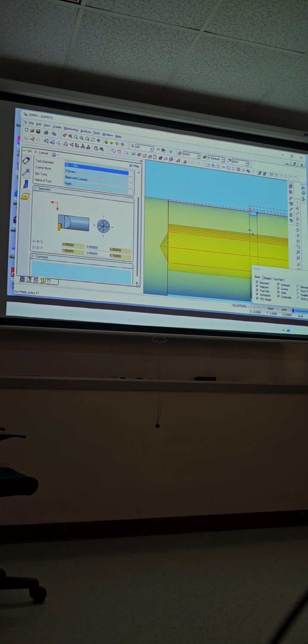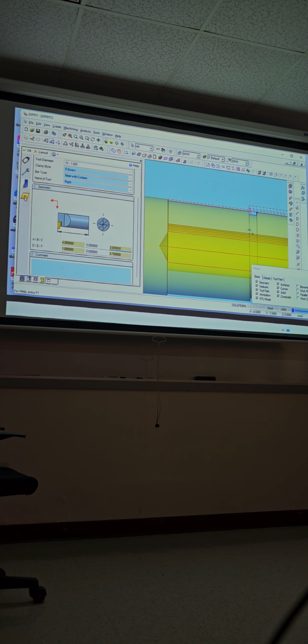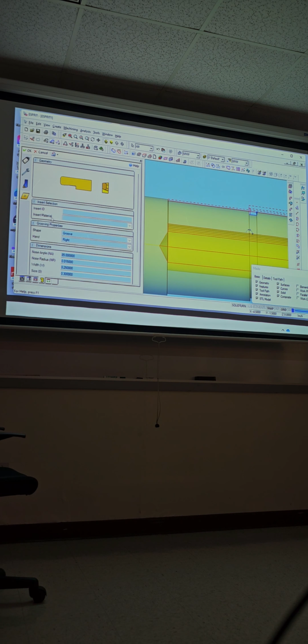All right, so over here, how far do I need on that tool? You're only going in 2 inches, so maybe 2.5, 3 inches? 3 inches, very good, guys, very good. You don't need 6 inches. You do this 3.0. All right, you're an insert rock star. Groove shape of that insert, full round. Full radius.